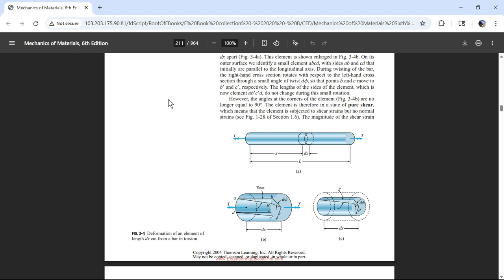Moving this one slightly up is enough movement, from a material mechanics perspective, for that to fail. We're talking very small, like the tank. The tank can squish in 1 inch before it fails. A 20-meter tank can lengthen by 1 inch before it fails. That's wild. It's not very stretchy. And then metal, like I said, well, I didn't say this, but you can stretch steel to 30% because it stretches like taffy.